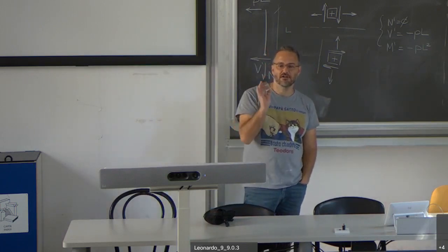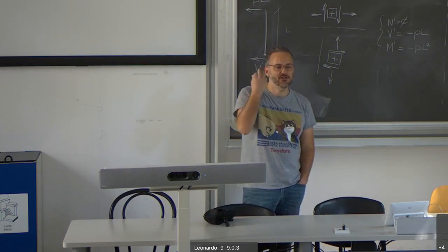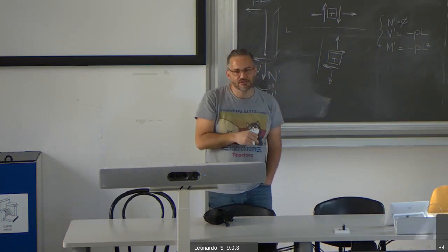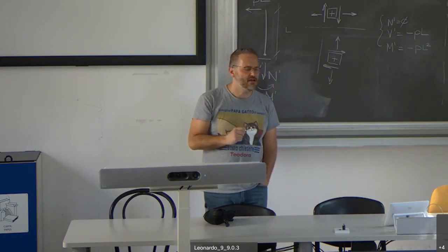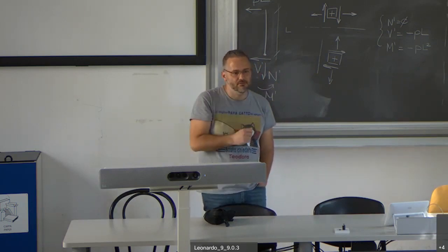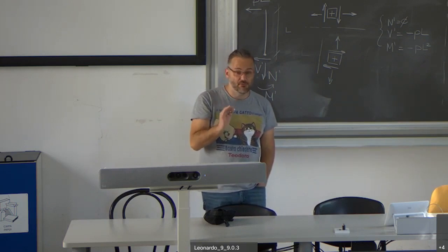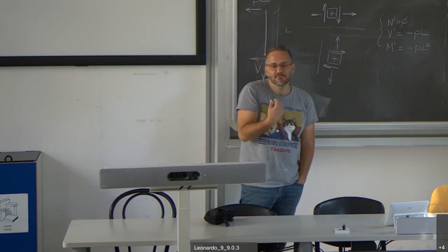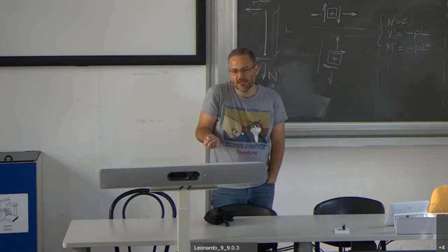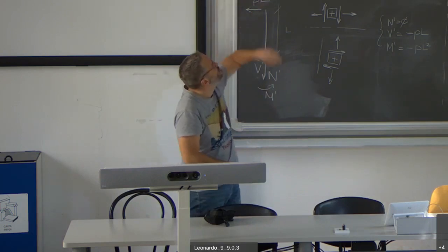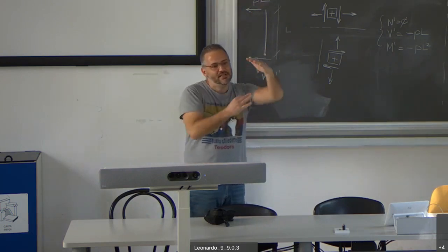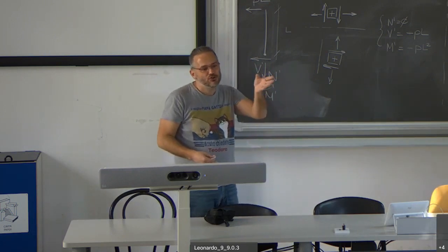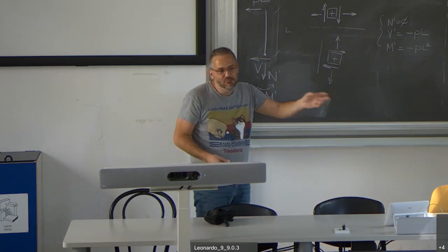You see how you struggle by figuring out whether it's tension. And suppose if I asked you, what about the shear force? Is it right that way, so clockwise, or will it be counterclockwise? And what about the bending moment? It's not so easy to see a priori. Okay, I maybe can, not because I'm smarter than you, but simply because I have more experience. So I know that that portion of the structure is basically a cantilever, just a crooked cantilever. So it has diagrams which look like the cantilever with some changes.